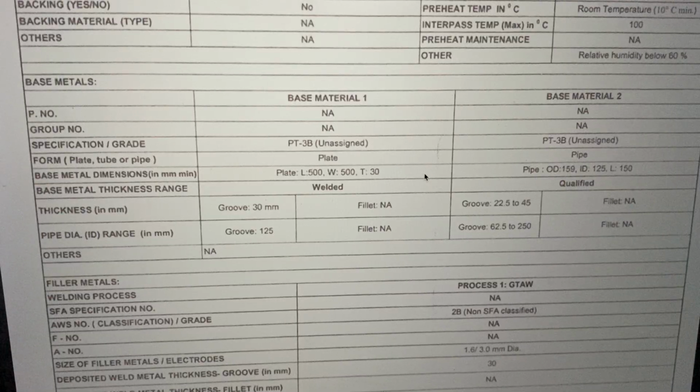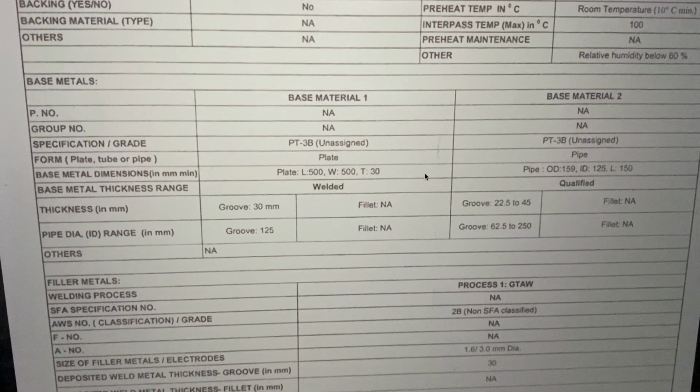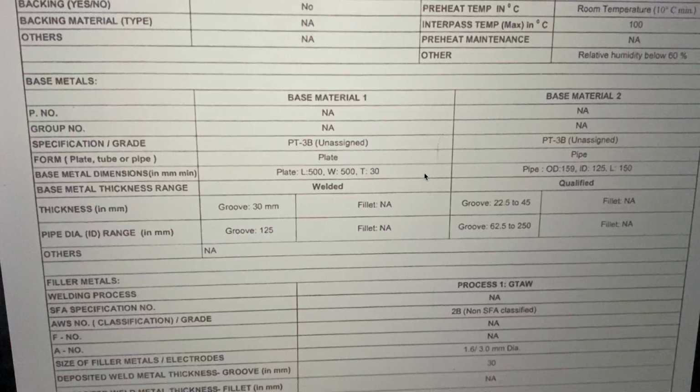properties. Or we have different alloys altogether, not the ferrous alloys but nickel based alloys, titanium based alloys, cobalt based alloys, aluminum based alloys, or combinations of those, which are classified in different P numbers. So since the material is changing drastically, it is an essential variable in our WPS or PQR. Next is the group number.